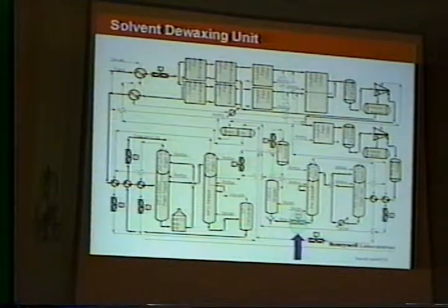And any individual PID controller is actually a rather small piece of the puzzle, and that's shown with that little highlighted circle on the right bottom. So it's still part of the picture, but it's not really a big part of the picture. But actually, the issue is that even problems at this level of complexity and scale are now very readily solved in the process industries, and this is well within the state of the art. This is fairly established technology, to be able to solve a problem at this scale with one multivariable controller. These controllers tend to be more effective controllers. So from the point of view of future vision, actually this is already very readily available.